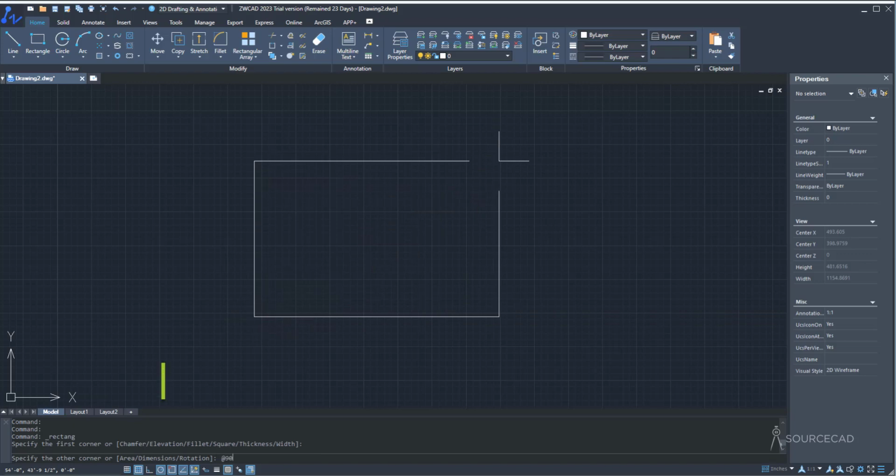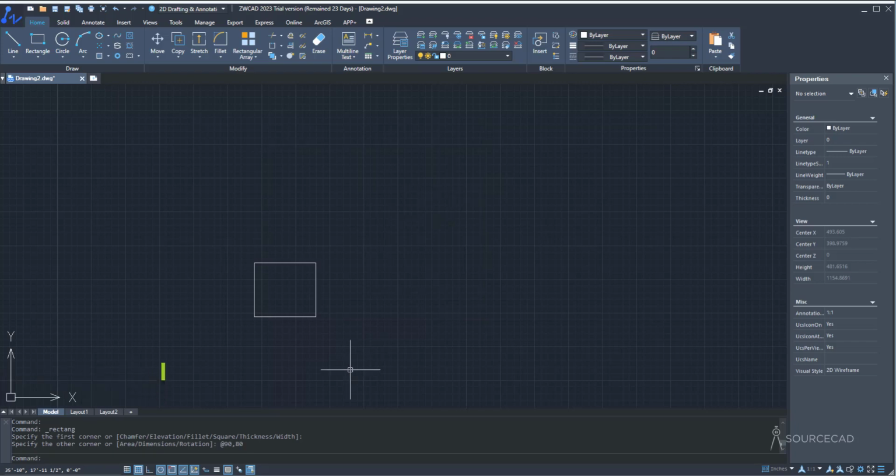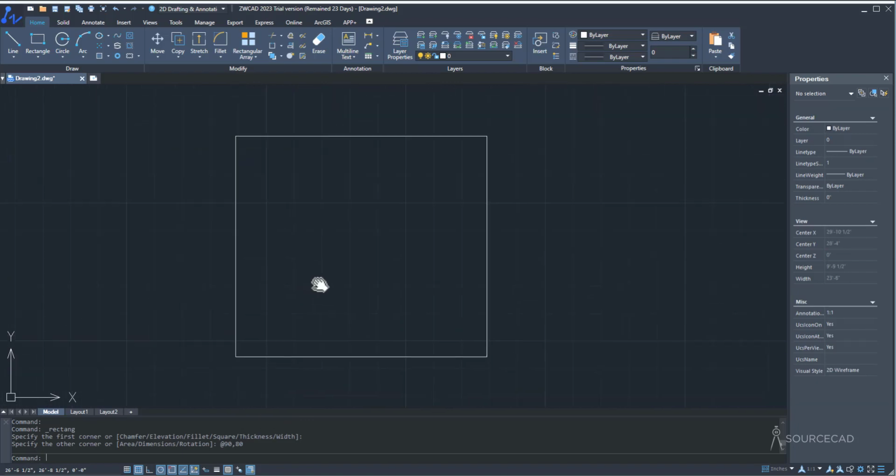So at 90, comma, now how much width do you want for the two stairs? So in this case, I think 80 inch is just fine because we'll add room for the railings and other things. So 90 inch by 80 inch and done. You don't need to add the inch sign here. Simply type @90,80 and you'll have the rectangle.